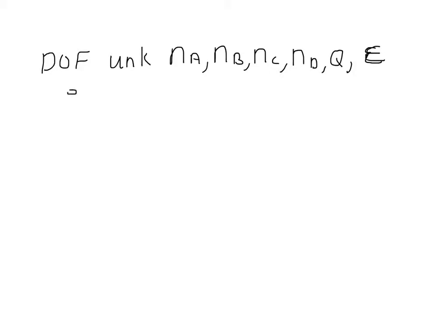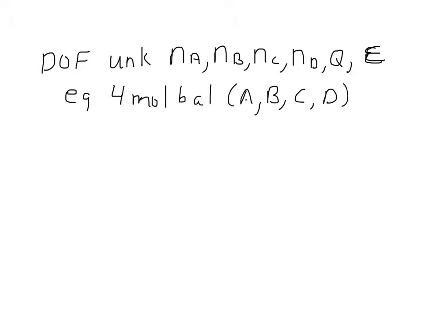The equations that we have available are 4 mole balances, one for each of our chemicals, A, B, C, and D. We have one process specification, that is the fractional conversion of A, and we have one energy balance.